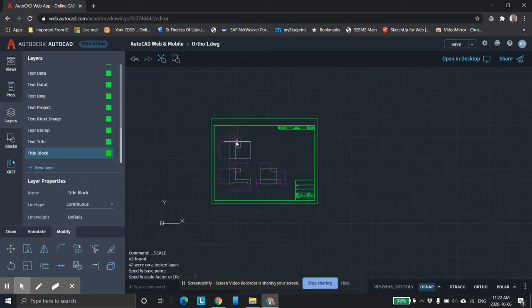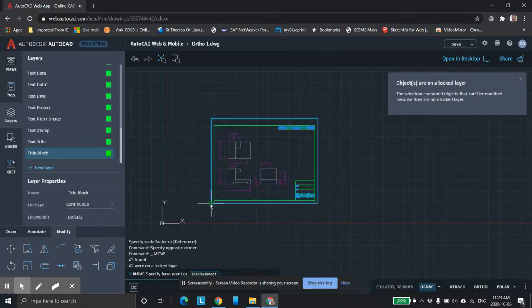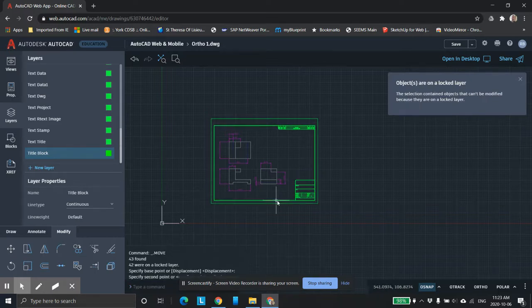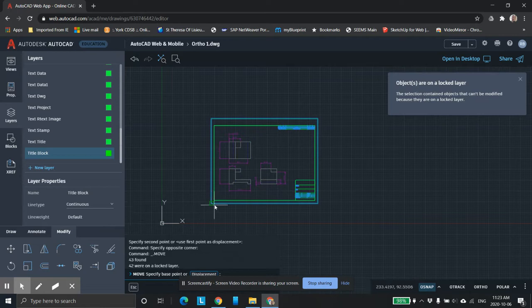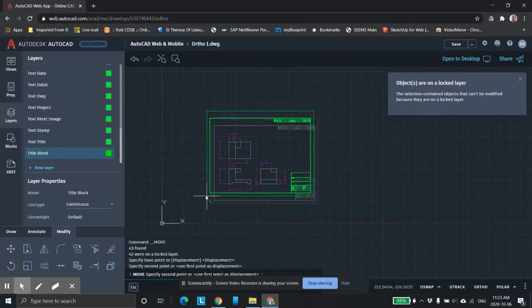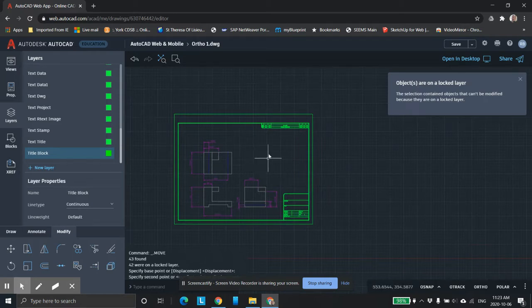And now we can change the position of it a little bit. Say we want to line it up. It's not quite lined up. Once we've changed the scale, if we made it bigger or smaller, then it's not going to be centered correctly. So what do we do? We can just come here like this, and we can move. We click the corner down here, and we can move it around into the appropriate position. So it looks something like there. It's jumping, you know why it's jumping? It's the O snap. What I just did there, it's O snap down. So let's do that again. Move it. Click the move tool. Let's take the O snap off so it doesn't jump where I don't want it to. Position it in a really nice position, something like that. Bingo, beautiful. Now I could easily put my isometric view in here.